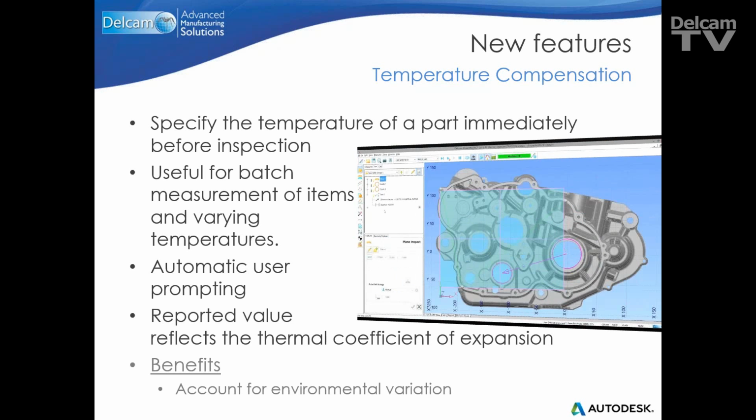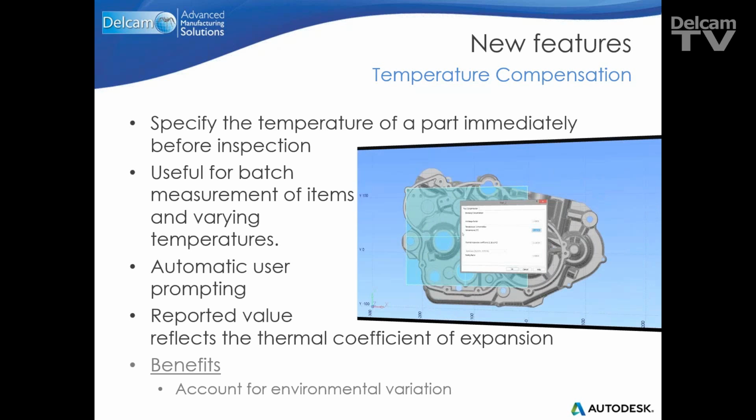For example, in the video, what Kieran did for me earlier in the day was he measured a component. He'd come into the factory and measured a component in the morning, took the temperature and said, okay, I'm measuring this component at 1 degree Celsius. It was a very cold morning. So PowerINSPECT allows you to input this information.